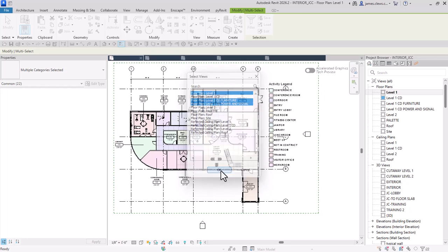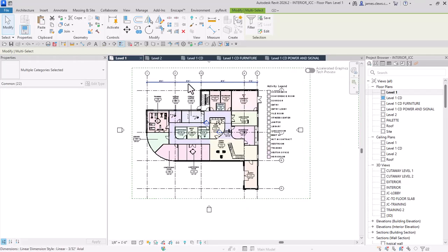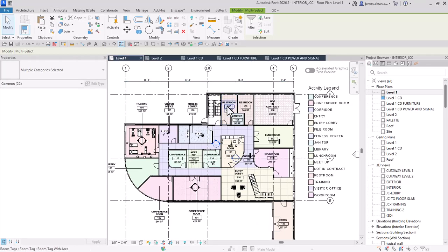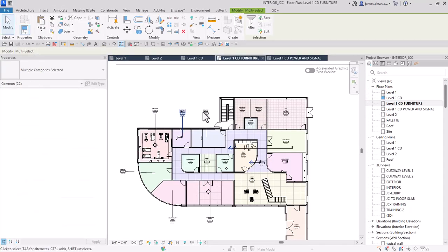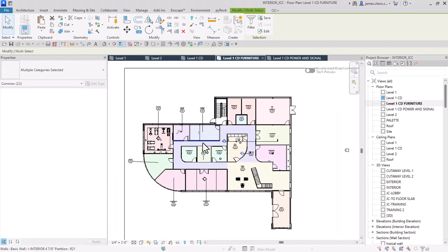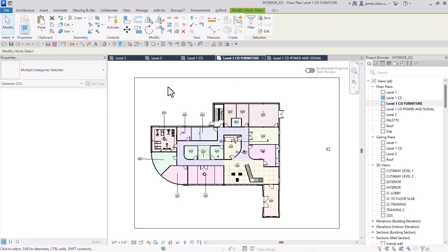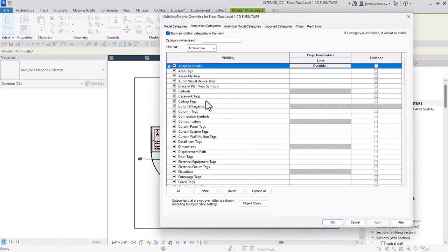So click on OK. Now if I look at these views, anything from the annotation tab that I had in any one view, I can get into here and here. Oh, I don't have the grid switched on, that's why. So let me do VG, annotation.